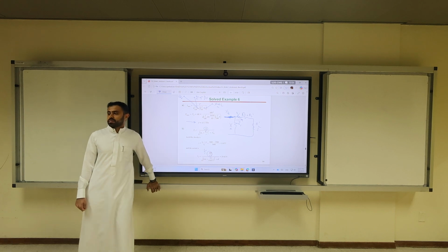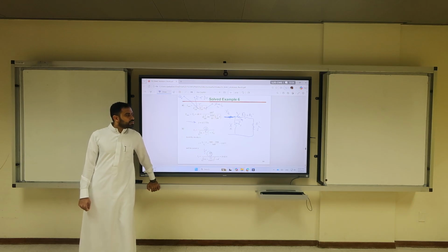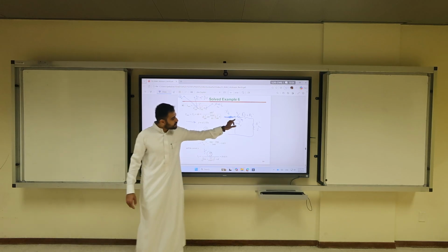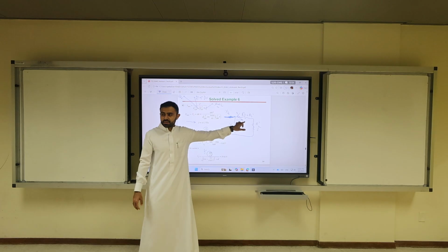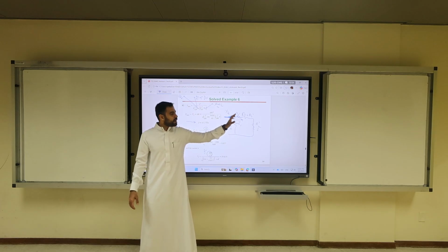Yes. Shouldn't both of the currents, the starting current, go to the XM? No. XM is very, very small, so we ignore it. Yes, ignore it. But the starting current, from the circuit's point of view, it's this current. Okay? Because we use an approximation.